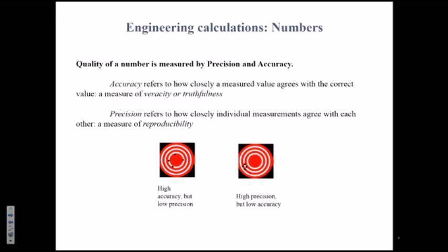But if it is made from another material that has a large thermal expansion and you use it in a hot area, it could expand, right? So your inch ruler has now become incorrect. No matter how accurate it is, no matter how precise it is, how many gradations are made on it, now it has deformed, it has expanded. So anything you measure from it is going to be inaccurate. It may be very precise, but it is going to be very inaccurate.